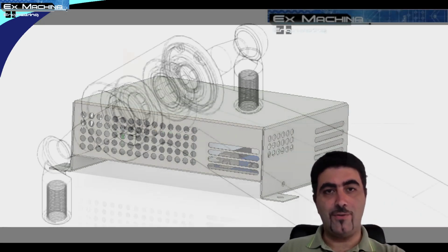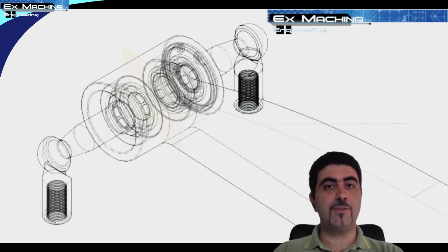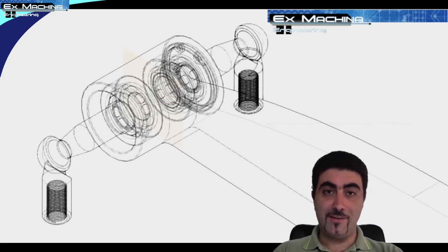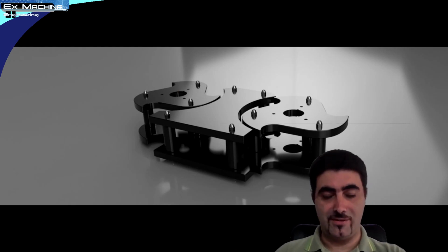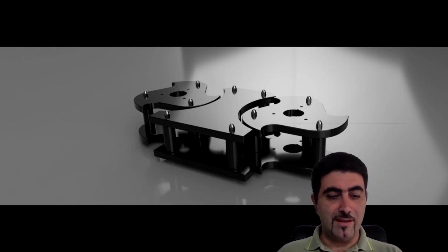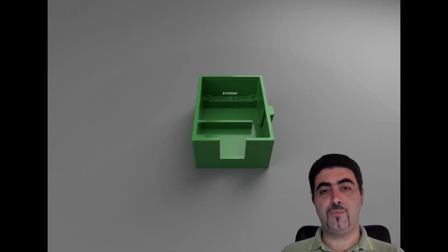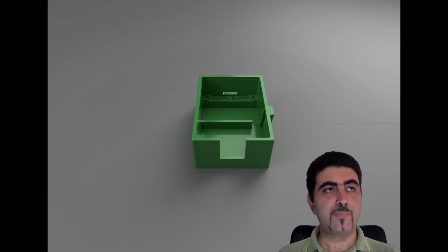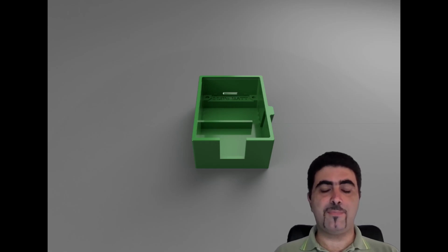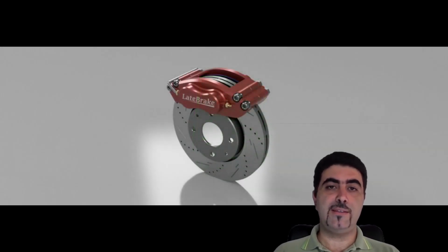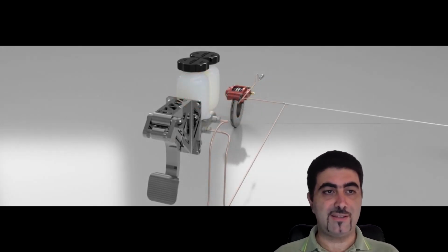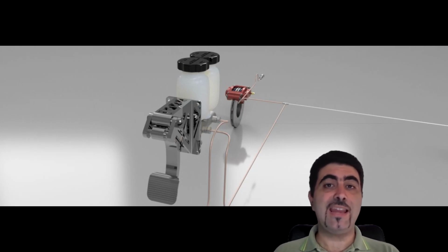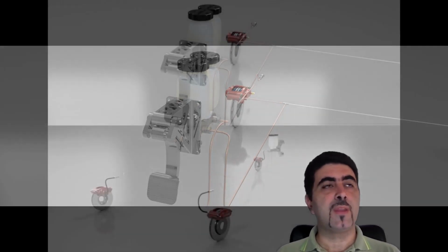Now, today we're going to talk about one of the most versatile and interesting features in Parametric CAD, and that is the sweep function. Okay, now the sweep function, what it does is it takes a profile and creates a solid not by sweeping it along a straight line like the extrude command does, but sweeping it along any path you choose, right?